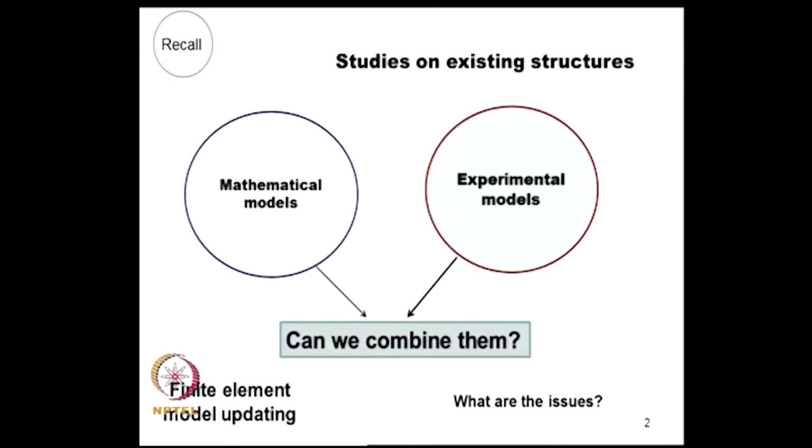We may assume isotropy, homogeneity, linearity, geometric nonlinearity, hereditary nonlinearity and so on and so forth. And we postulate certain idealized boundary conditions, and in structures with jointed elements we assume certain features associated with the joint behavior. So, there are many, and damping is another major issue where significant idealization is done.